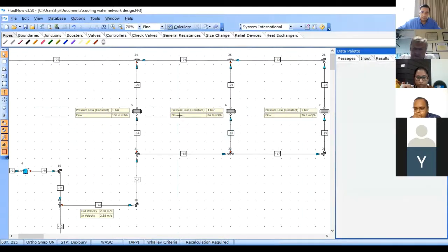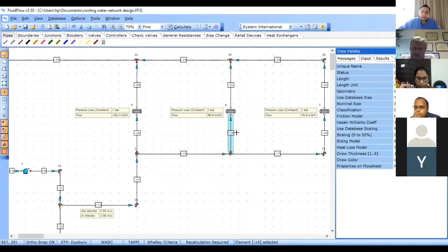Dr. Joseph was telling you can play with the pipe diameter. So here we have got a 5-inch pipe. It'll have some delta P. If I go for, say, an 8-inch pipe, there will be less delta P, so that it will push a little more flow. But again, it will be an expensive option. So that's why we will not go ahead with that, right? Yes. So let us proceed with putting one restriction orifice in the outlet.